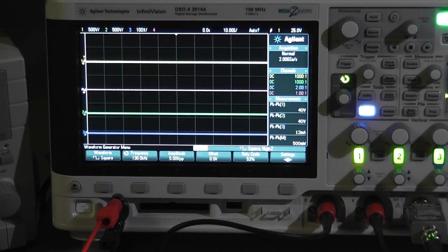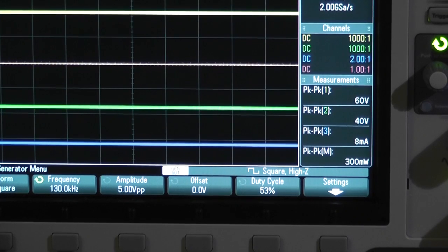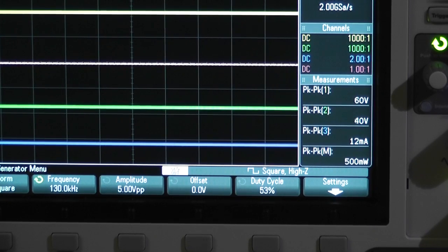And because I'm already connected to the big coil with my probes, I'm picking up quite a lot of power fluctuations. If I zoom in here, you can see that I have set up the system with peak to peak as the main measurement. This peak to peak measurement will have to be normalized later on. So we average it, bring it down to a mean value, and then I go even further down and apply RMS. I have to divide the values by the square root of 2, and later on that counts for voltage and for current.